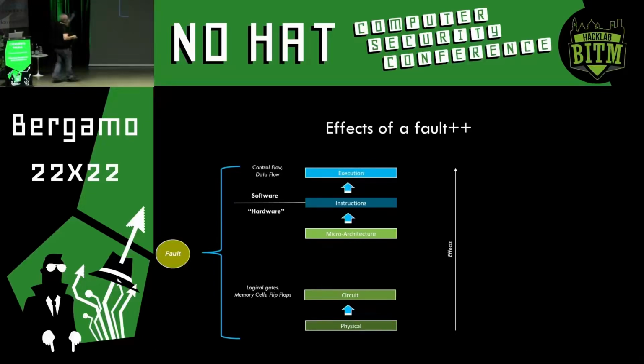That's what basically you have. We like to add an additional subsystem in the middle, which represents whatever is not a CPU, but is a valid subsystem. So for example, at this level, you can do glitching of things which are not a CPU. You can actually open a JTAG with fault injection, which is closed. And this has nothing to do with the CPU. There is no software being glitched. You can actually glitch an OTP behavior, one-time programmable, the configuration in hardware. And this has nothing to do with the CPU. So you can affect the hardware logic, basically how it works.